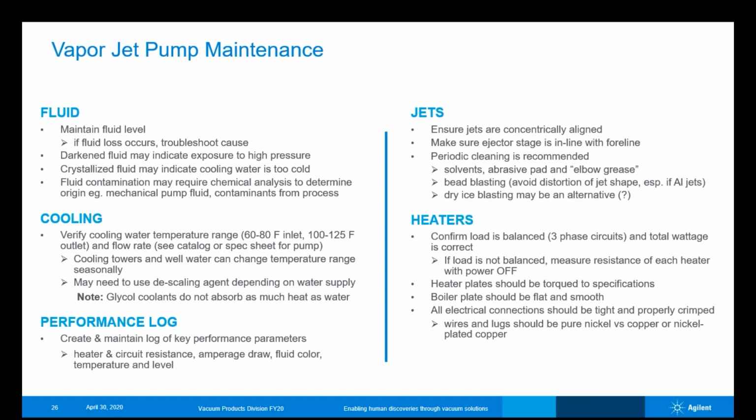Recently, I've talked with our colleagues in the customer call center here, and they've mentioned some of the customers are using dry ice blasting as a sort of an inert way of doing that bead blasting without the potential for damaging the mechanical surface of the jets, but also it has the benefit that nothing ever stays in the liquid phase, that these will sublimate directly back into gas phase. And I'd really like to follow up on that. If anybody in our audience today is using dry ice blasting to clean up jets, I'd appreciate if you could drop me a line and give me some input on that, because I'd really like to incorporate it into our future training sessions.